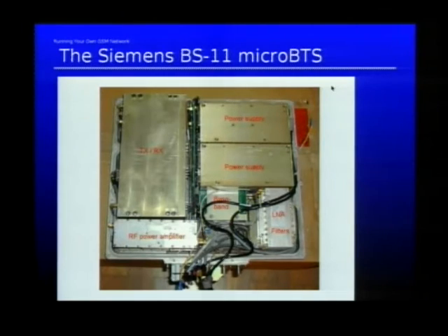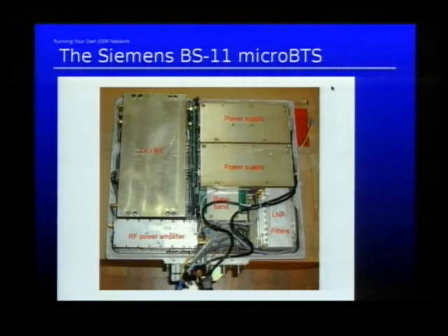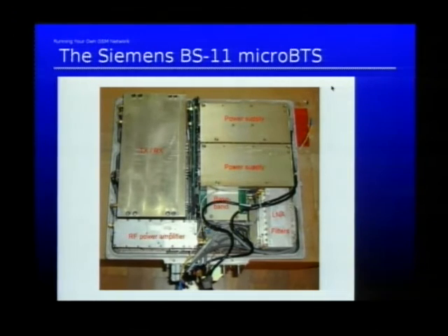There are the filters and the low noise block, which is connected to the antenna. There is the baseband part, which basically processes the digital streams which were already demodulated, or processes the data which have to be modulated and later transmitted by the system. We have several huge parts on the left, which are the transmitter and receiver. You only see this large block, but actually they are stacked. There are 4 boards stacked over each other, and they contain this information.